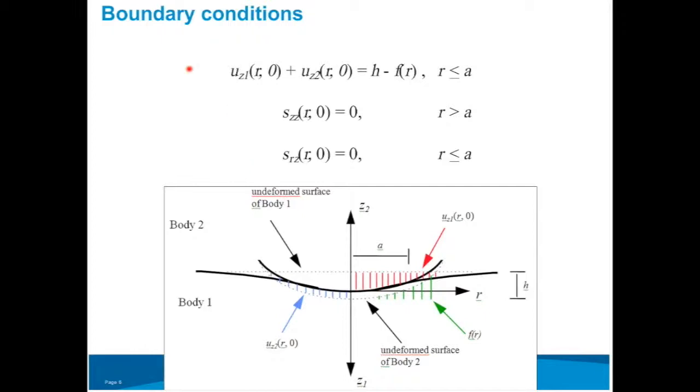And then the other place it would break down is if this is not quite true. There was an important publication by Farr, Bolshakov, and Hay, and that's actually my husband, Hay, that's not me, where they showed that this particular boundary condition is not entirely adequate for modeling physical indentation experiments, and they propose a very useful slight modification to Sneddon's stiffness equation based on that observation.